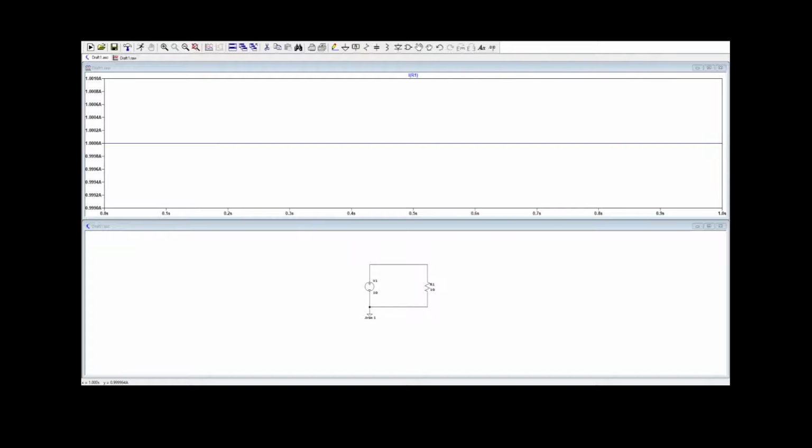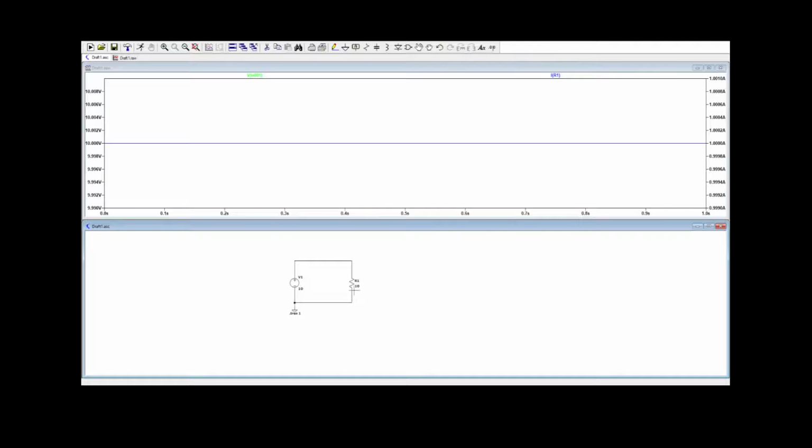That's kind of the most important formula in circuit theory. You're going to be using it a lot. It does have some limitations though, so I'll go into that right now. If I left click on this node here with my voltmeter, and I hold and move my cursor to the ground node, you see how my other probe turned black. Now if I release my mouse click, it'll give me the voltage across the resistor.